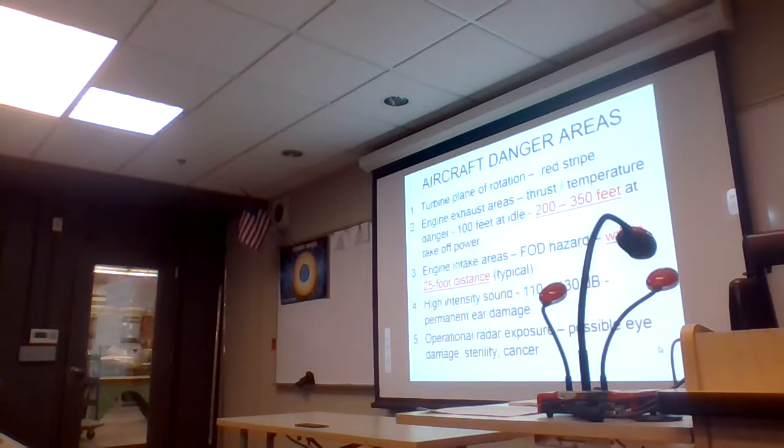Operational radar exposure: possible eye damage, sterility, and cancer. On some aircraft, the radar beneath the radome is inhibited from operation by the squat switch on the landing gear. However, don't always count on that. Just be aware that if you're working in and around the aircraft and they have anything that emits radar waves, you can potentially absorb that, and it can cause severe health issues: cancer, sterility, possible eye damage, so watch out.